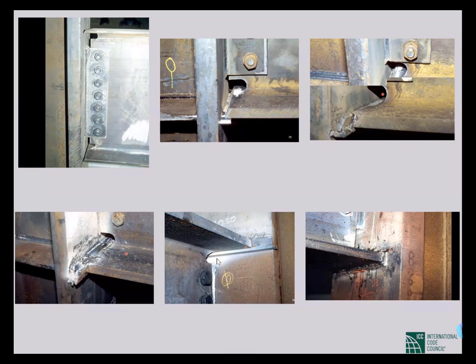And in the last picture, you see the bottom flange is completely welded. The backing material has been removed, the weld tabs have been removed, and it has been ground properly. So this is the complete CJP welding.